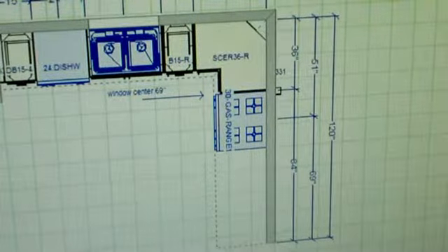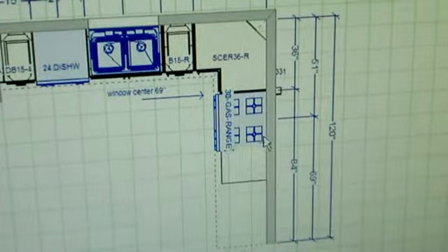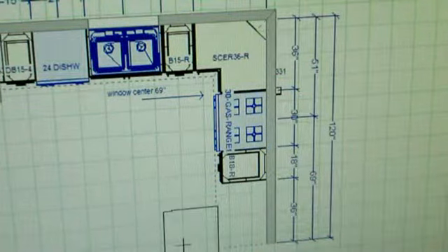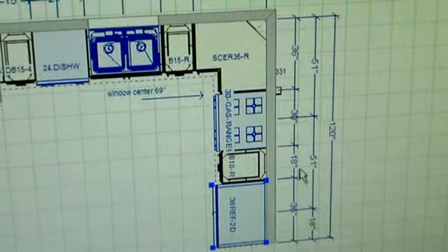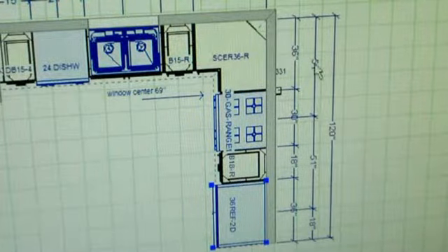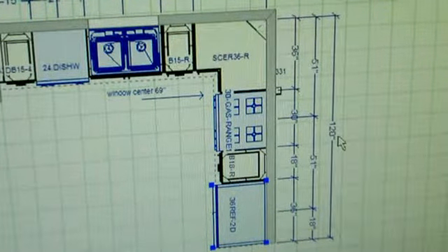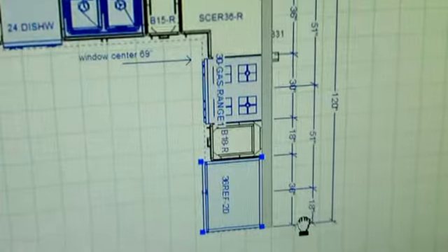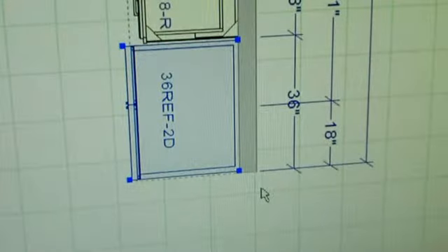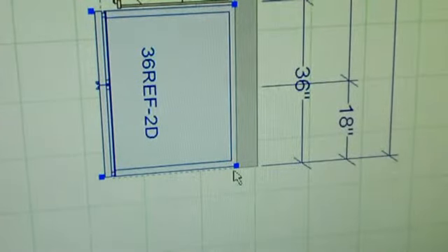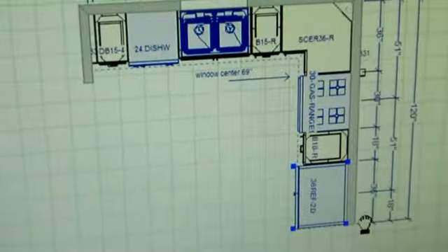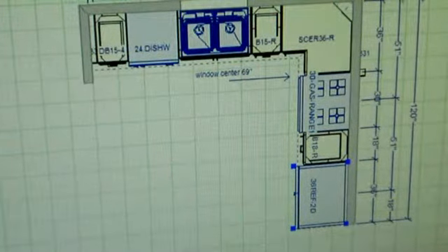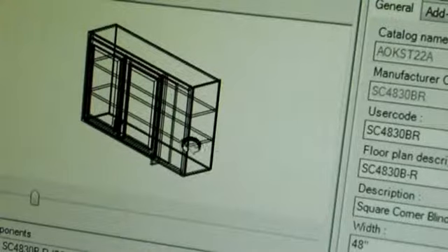If you look at the balanced space on that 120 inches, I already know I'm going to use a 36-inch refrigerator, so it's pretty much a natural that I've got the 18 inches left. And then with my refrigerator on the end, remember, the actual wall dimension is 122 inches. So I have 2 inches of what we refer to as a reveal. And it's good to have reveal next to tall especially, because if a wall's crooked or there's any odd variations, you can accommodate that.